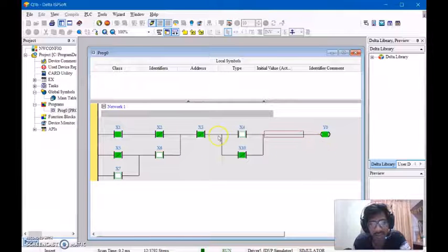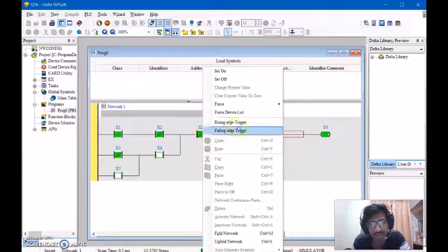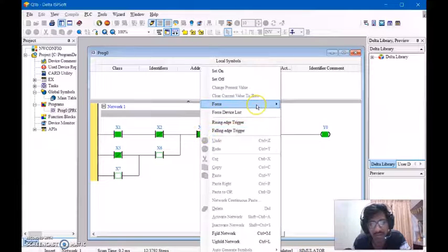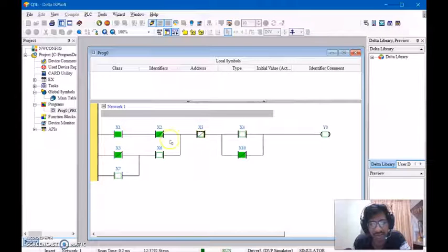As you can see, I forcefully open a few switches so the light will be turning on. For example, if I force off this, it's already in. If I turn on this, the supply won't pass through, as all 3 lines go to X3. So X3 plays the most major role here. If this does not transfer any supply, Y0 will never light up.